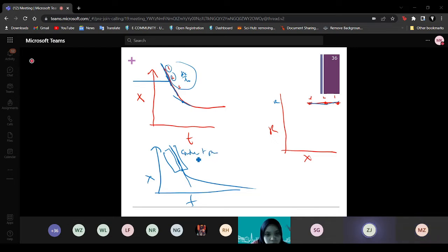This is the normal observation. After the slope is changing, then it's falling. The dx over dt is going to change, decreasing and decreasing. Okay, so these are things that you might need to take note of so that you can produce a very nice rate of drying curve.